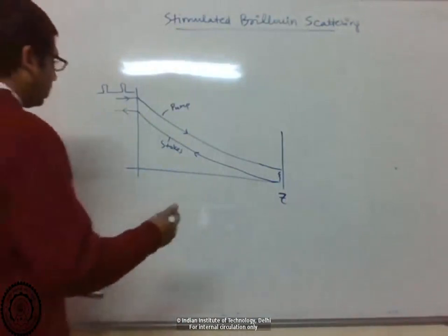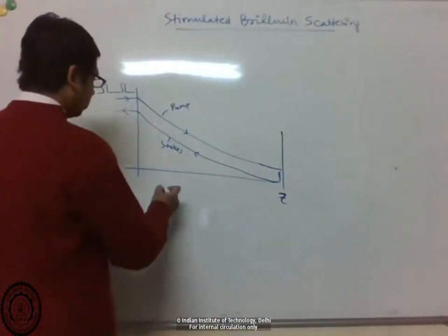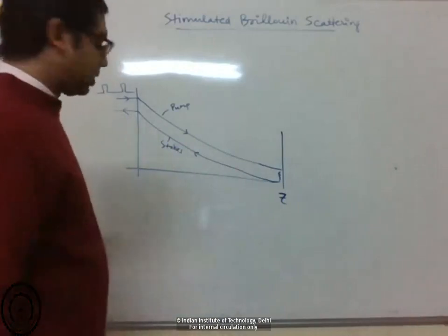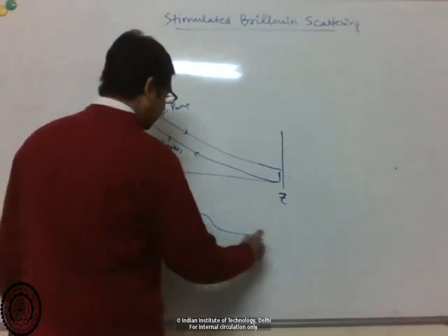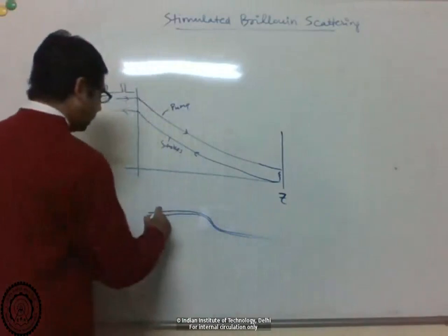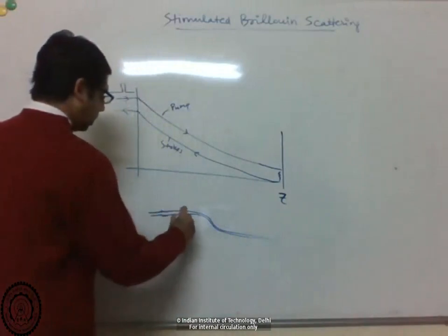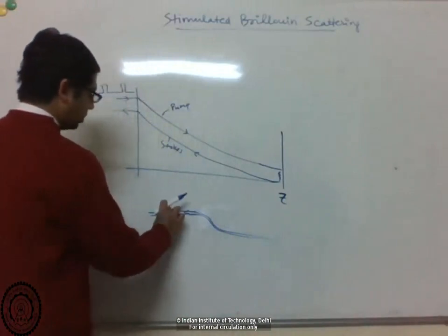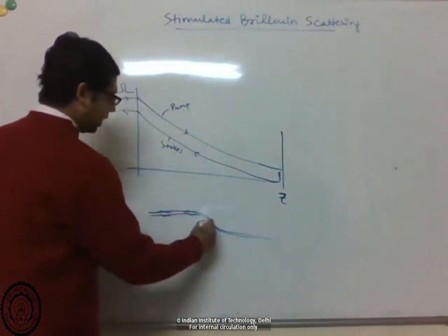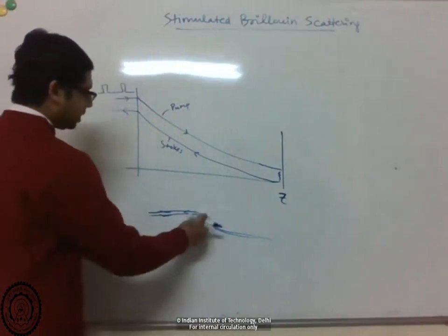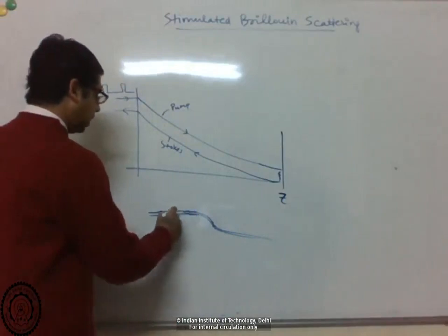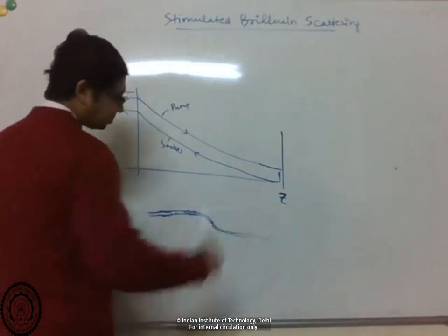Before that, in the initial days, one way SBS was avoided on its own was that fiber manufacturing was not perfect. So there were inhomogeneities along the fiber length. For example, the width of the core had irregularities, there were bends in the fiber causing stresses, or the impurity concentration kept changing.